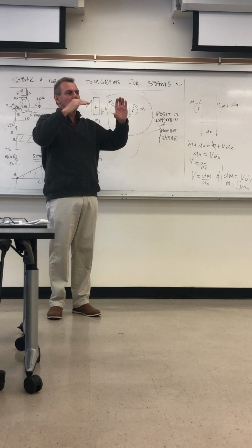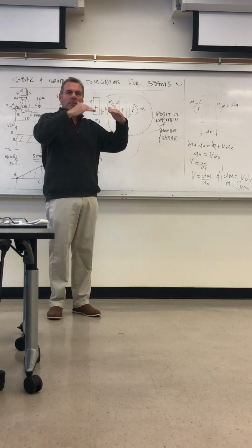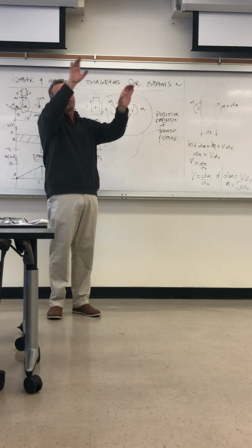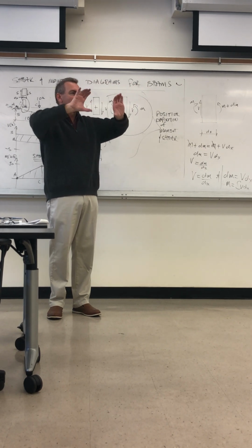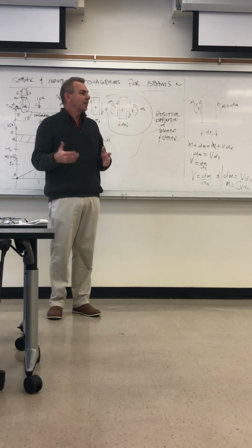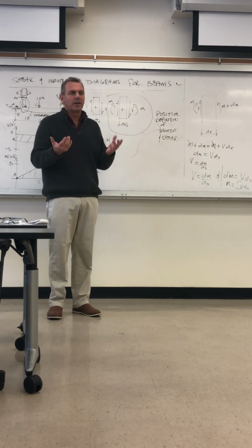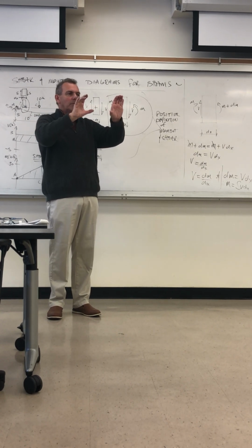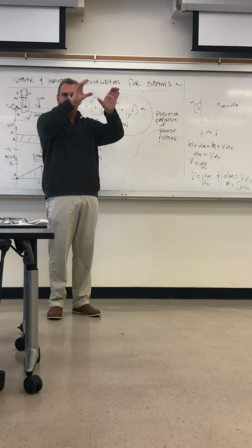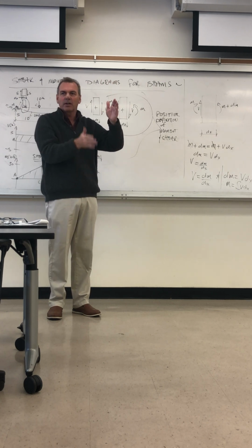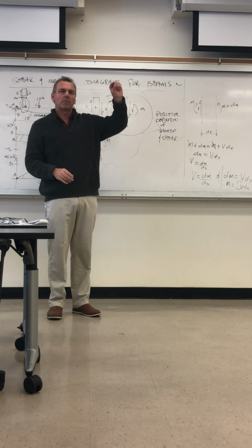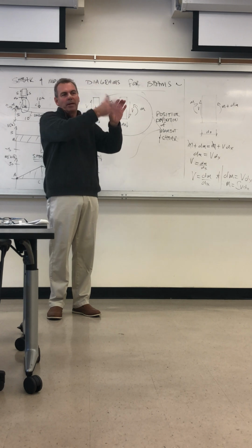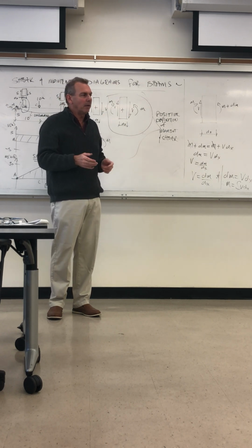The flexural stresses, the bending stresses, increase from the neutral axis up and decrease down. So if I'm bending it this way, the top fibers are all in tension, the bottom fibers are getting shorter and they're in compression like that. And yet there's this relationship between the two. They seem very different. And if you take a cross section, the bending stresses, if you integrate, sum up all those flexural stresses, these are stresses in this direction on a cross section, multiply those stresses by their little areas by their moment arms, that has to sum up to the applied moment at every cross section also. Everything's perfectly balanced based on statics.